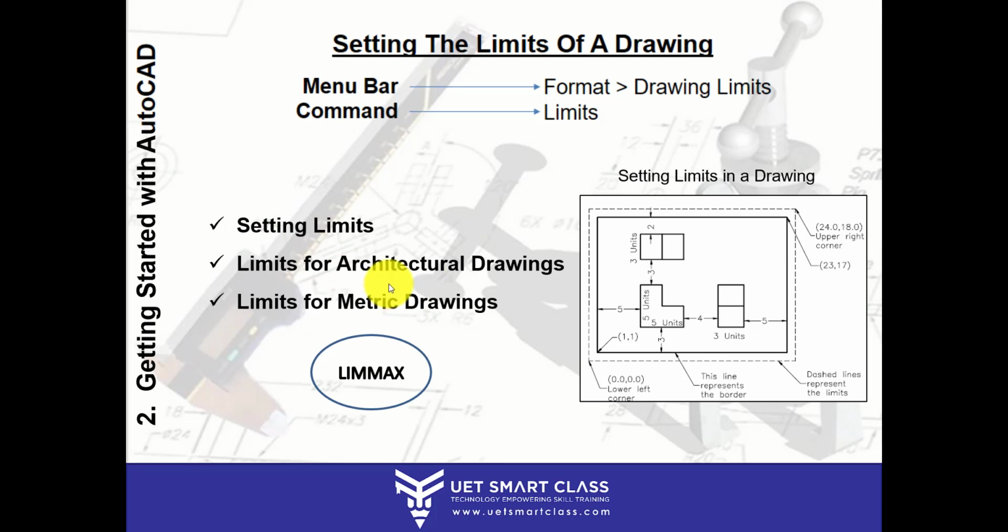For this, you can set your scale also. You have to set your scale, and accordingly, you have to set your sheet size. Majorly, we work on 1/4 scale. Sometimes we work on 1/8 also. So accordingly, you can set your limit scale, and you can also set the sheet size accordingly.